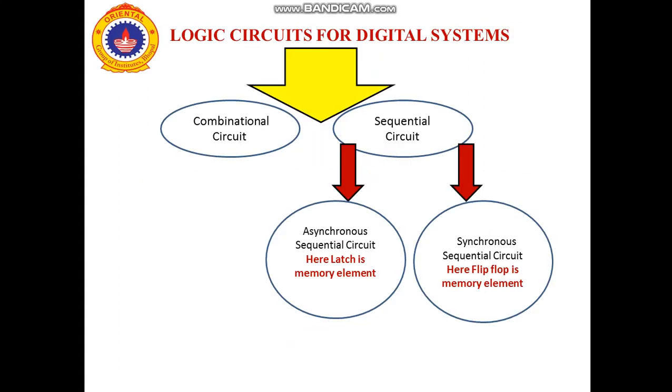The logic circuits for digital systems are basically divided in two categories, the combinational circuit category and sequential circuit category. Further, the sequential circuits are divided in two other categories, asynchronous sequential circuit and synchronous sequential circuit. In case of asynchronous sequential circuits, we use latches as a memory element, while in case of synchronous sequential circuits, we use flip-flops as memory elements.